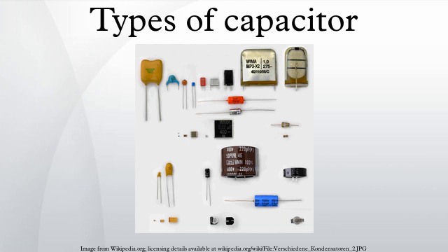Ohmic losses, ESR, dissipation factor, and quality factor. The summarized losses in discrete capacitors are ohmic AC losses. DC losses are specified as leakage current, or insulation resistance, and are negligible for an AC specification. AC losses are nonlinear, possibly depending on frequency, temperature, age or humidity.